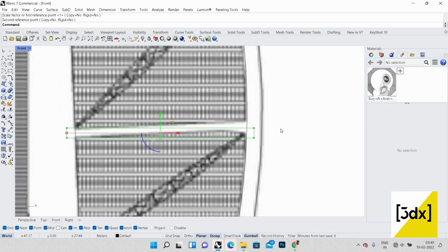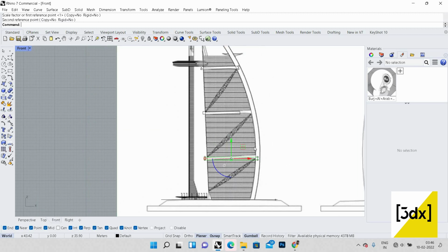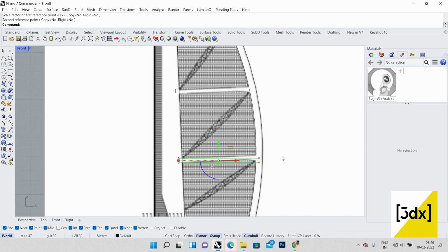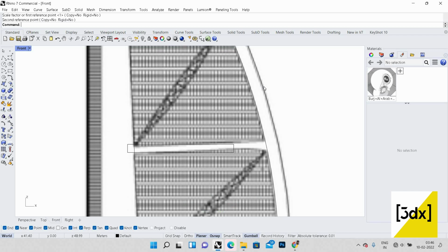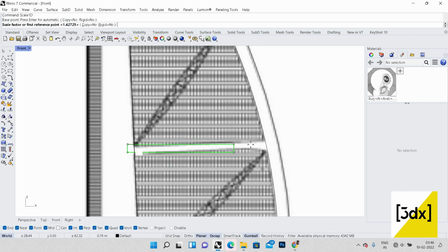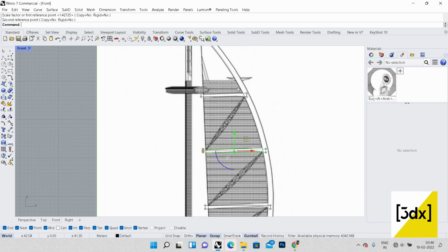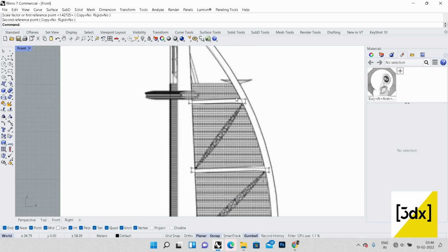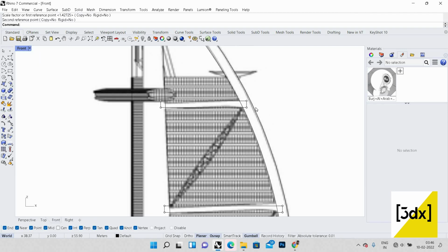It is similar to SketchUp, where you can scale a single object. So this is the same way. You can use scale 1D to scale on a single axis, whereas scale 2D is double axis, and normal scale is 3 axis, so it's usual. So I'm using scale 1D, dragging this over here so that it crosses this line and intersects with the line so that I can trim it properly.